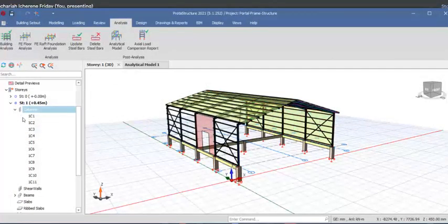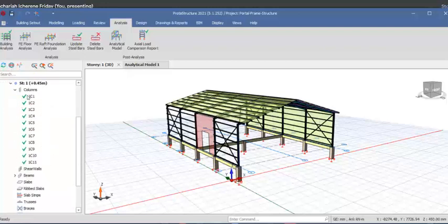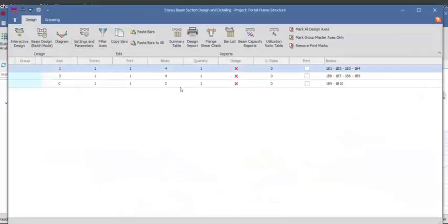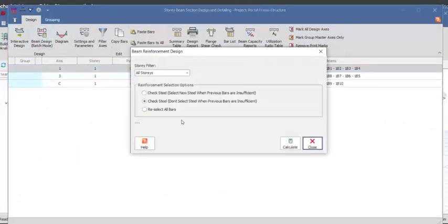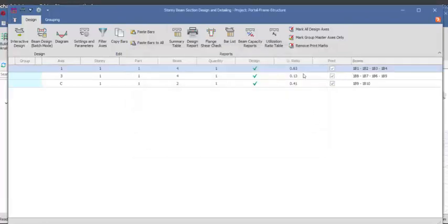Check the beams as well. So we can just click on this refresh, click on this refresh, and then get back to check this. See, now it has been checked with green color to show that this has been designed successfully. So get back to the beam, right click, and then we use the active story option. So we have like 3 beams right there. You have to select all with design. So click on the close option. This has also been designed successfully.